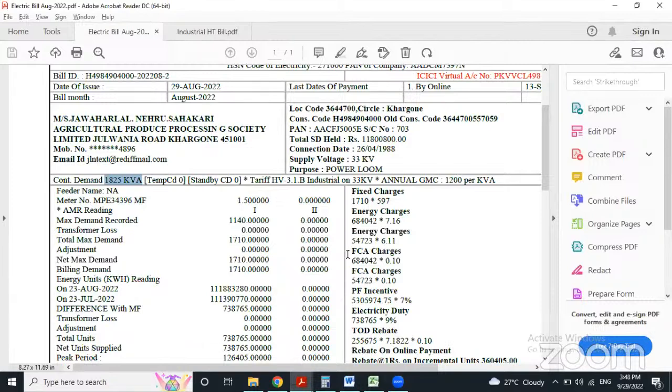Once you determine the PV plant capacity, you have to go back to the basics, that is, whether you want to go for an on-grid system or an off-grid system. Generally this is for an on-grid system. Then in the on-grid system, which panel you will take, how many panels, what the string combination will be, which inverter you select, and which ACDB or DCDB you are going to select. The cable sizing and everything comes into the more detailed designing of the PV system.